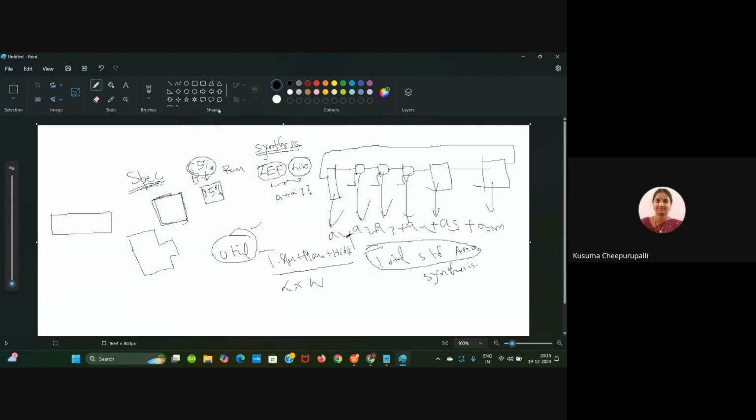They might be giving more area to standard cells. More area to standard cells or less area to standard cells? 85% utilization in the sense most of the area must be utilized, no, sir? Exactly. The standard cell areas cannot be touched. It can be swapped, but that's not the way to increase the utilization. Utilization can only be increased manually by changing these dimensions. Okay, so the dimensions are being shrunk.